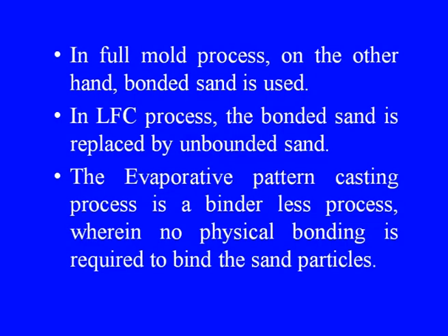In the full mold process, on the other hand, bonded sand is used. In the LFC process, the bonded sand is replaced by unbonded sand. The evaporative pattern casting process is a binderless process, wherein no physical bonding is required to bind the sand particles.